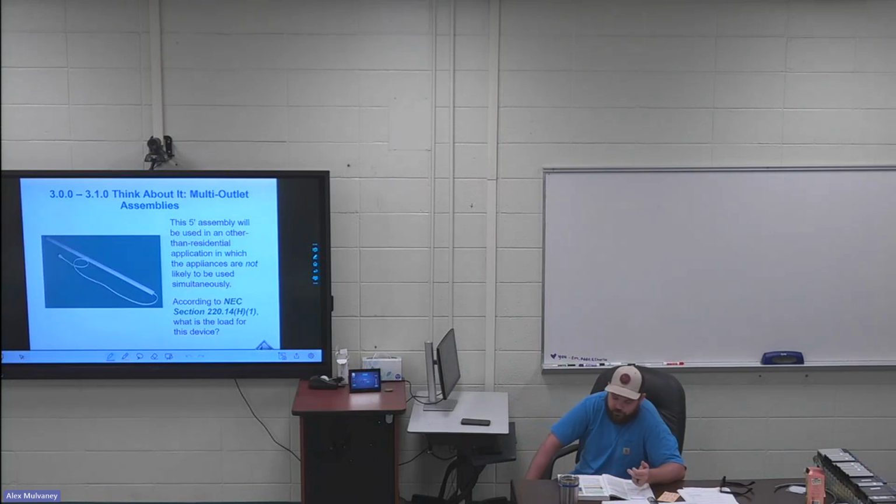The paragraph that's right under that note on page 19. NEC section 220.43 addresses the computed load of show windows when calculating feeder or service loads and requires that the total load be calculated at not less than 200 volt-amps for each linear foot of show window.